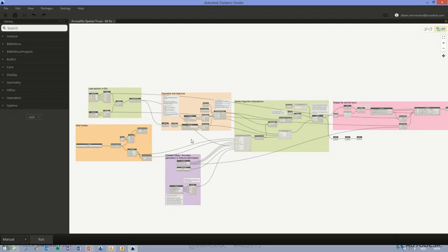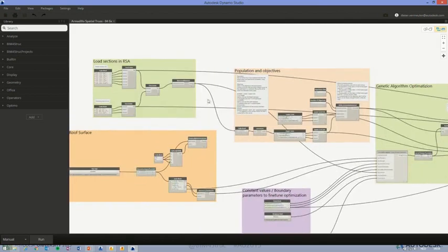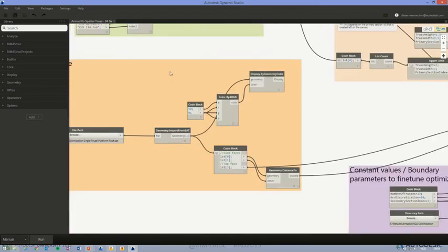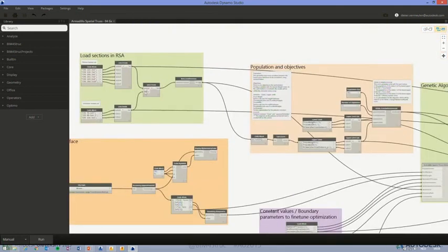Now, let's represent that problem a bit. In the next script, what is my objective? If you perform structural optimization, it's very important that you write this down for yourself. I want to have a minimal weight score. Second, what are my design variables? I want to change the truss height, the truss width, and also look at the primary members and change those too.